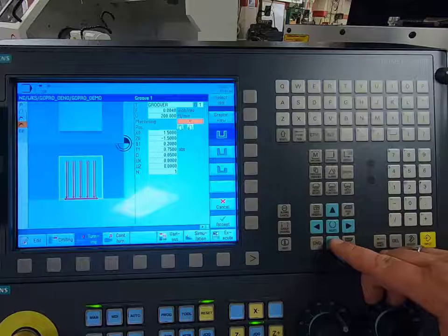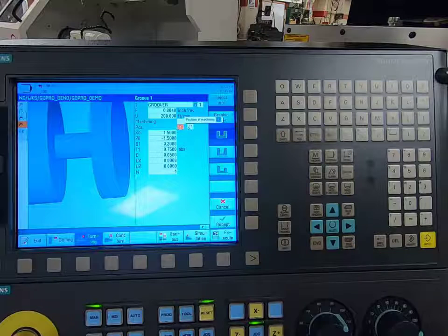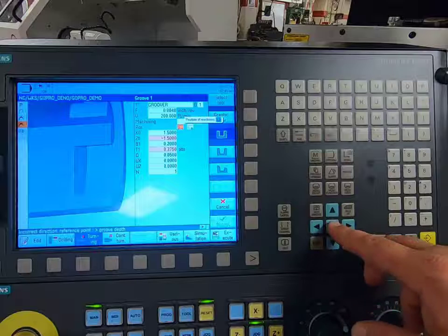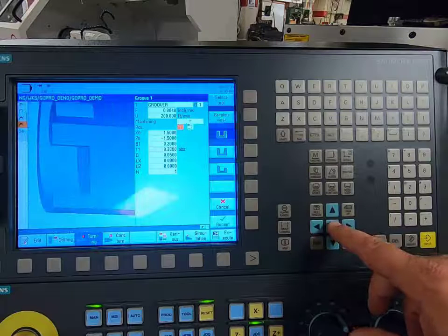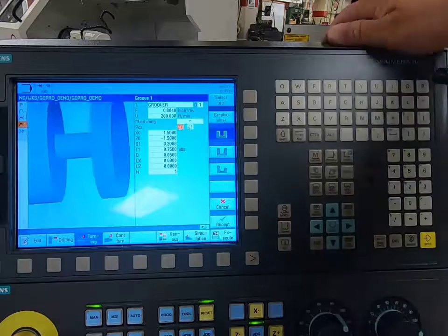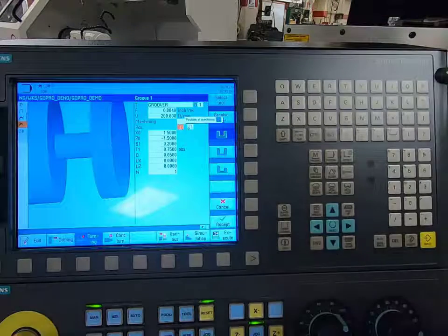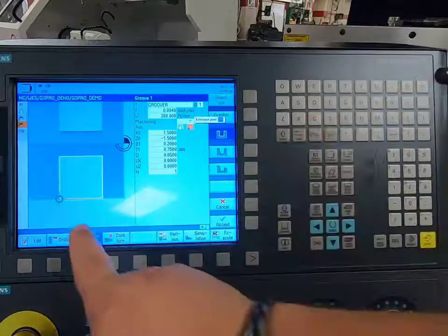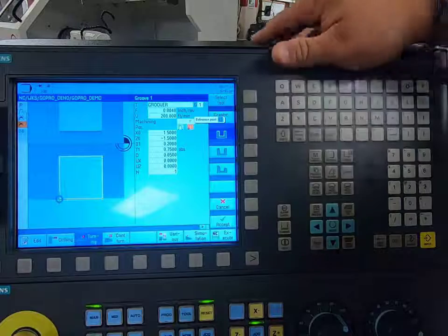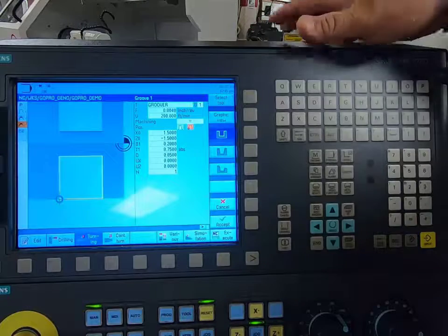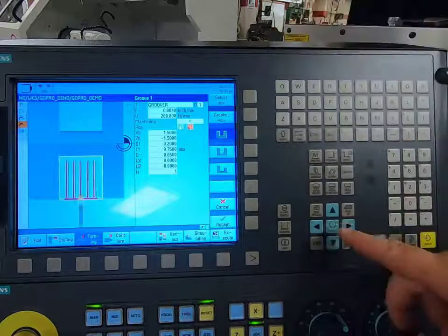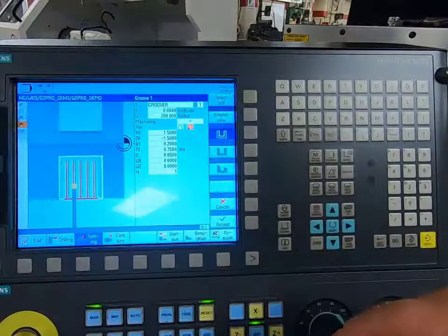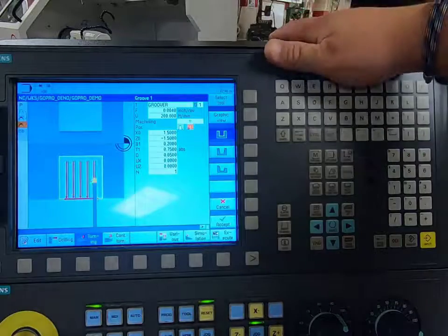Okay, so I got my roughing selected. Now right here you want to pay attention because I have the position of the machine. This is where the machine's at, how it looks. Obviously I'm getting some errors in here as I rotate it, so I want to keep it there because that's the type of groove I'm going for. If I arrow over, notice where this blue circle is. That is the left side of my insert, and it is the tip of my insert. If I move it around, it will move from here to there to there. So I have it in the correct location right now.